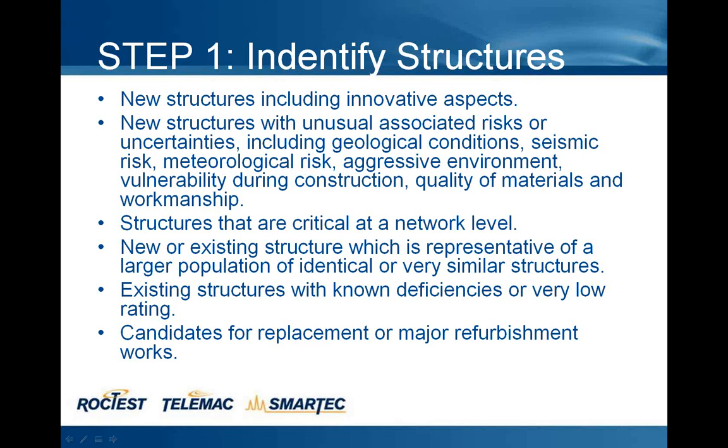Also, other good candidates for structural health monitoring are those structures that are critical at a societal level. So a very important bridge, maybe not by size or risk type, but a bridge that is important for linking two areas where people must really travel on that bridge, or a tunnel in a similar condition. Also, new or existing structures which are representative of a larger population of identical and similar structures.